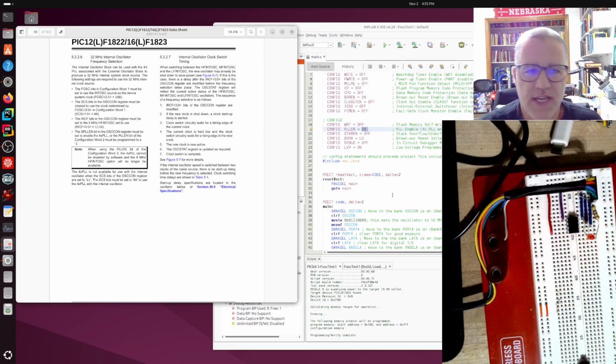So this PIC has a peripheral pulse width modulator that'll just run without the central computer part of it. So it'd be a little bit different than bit banging on off on off. This will just run independently of that based on the internal timers, and this clock speed controls that internal timer. So it does become important at times.